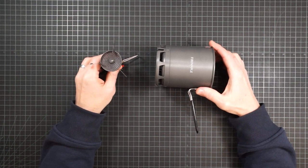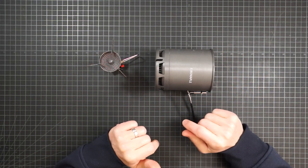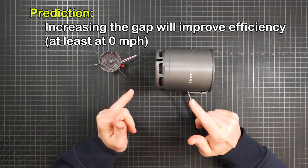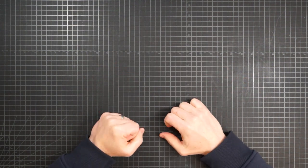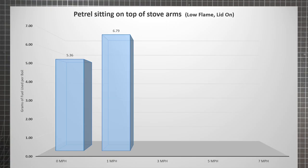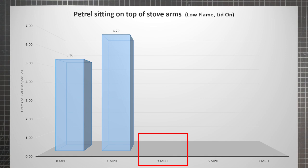The Petrel, as tested, had the smallest gap and the worst efficiency with no wind. Well, they say the gold standard for a theory is its predictive power. The prediction here would be that increasing that gap by setting the stove on top would improve its performance, at least at 0 miles per hour. Because I crave to please, I tried it out. On the low, the higher seat did, in fact, beat the performance of the closer fit, as predicted. A countervailing effect of this unprotected stance, however, is that performance will begin to suffer as the air starts moving. So I tried getting a boil at 3 miles per hour, but couldn't do it.